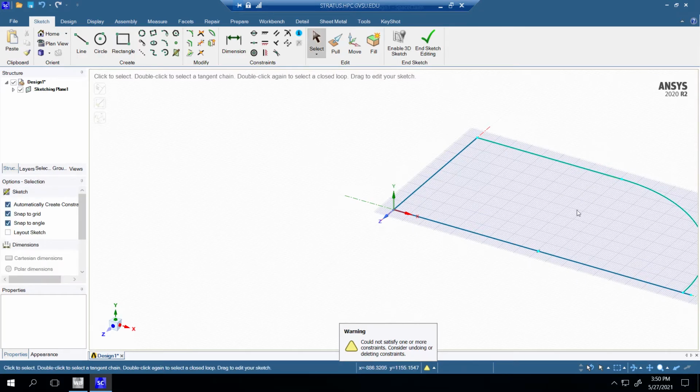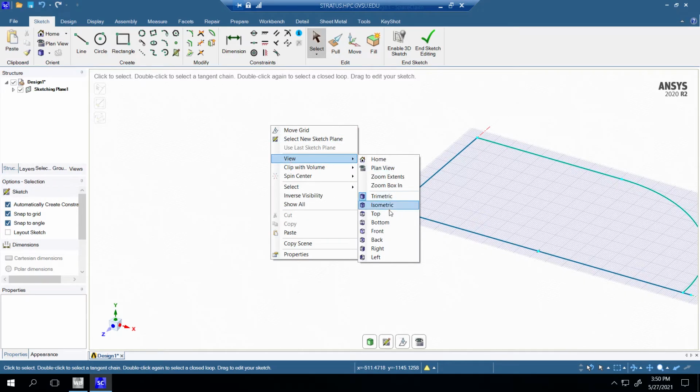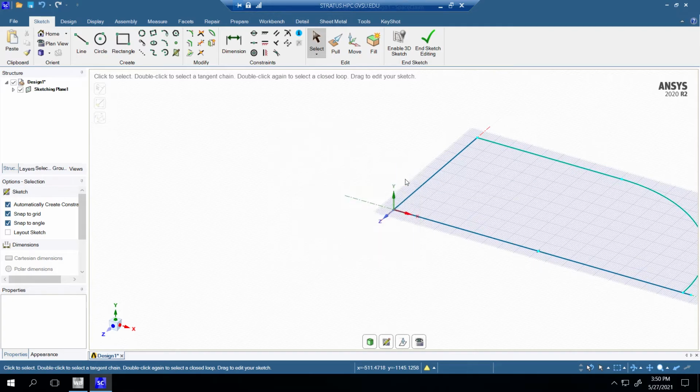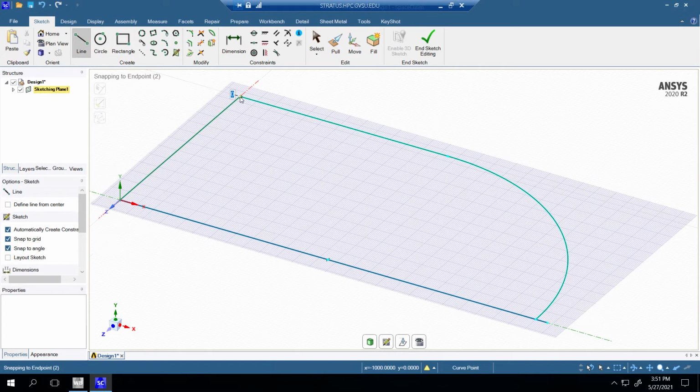All right, so I did this, but I need to make a face, and the thickness is going to be 10 millimeter. So I need to repeat this line. I need to have a line here, and extend that line. How much should we move? 10 millimeter.